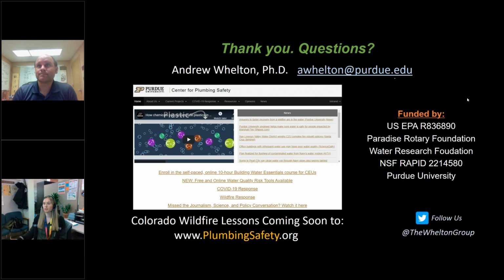Okay, great. Kind of along the same lines, this question says, does water pH or corrosivity of source water affect that absorption process? So, to our knowledge, water pH would only affect the dissociation of organic acids in the water. We're not generally concerned about organic acids. So the organics would have a proton, and at a certain pH, it would stay together, and at a different pH, it would kick off and be present as a proton in the organic acid floating around. So that only generally happens at certain pHs, generally not within drinking water ranges. So pH shouldn't affect it, but there haven't been good studies to really understand how pH would impact that process.